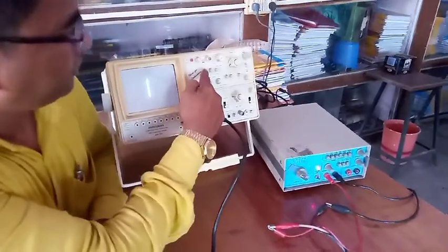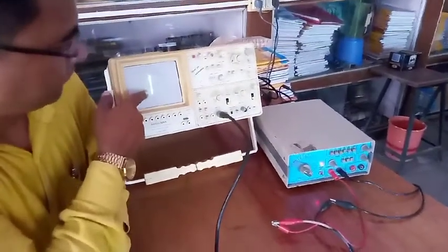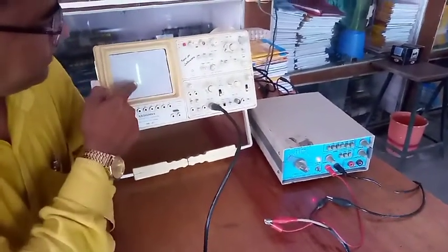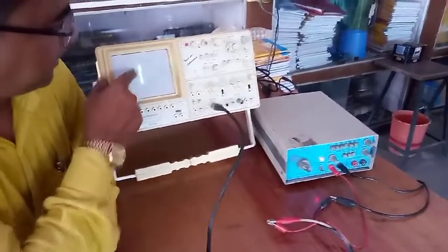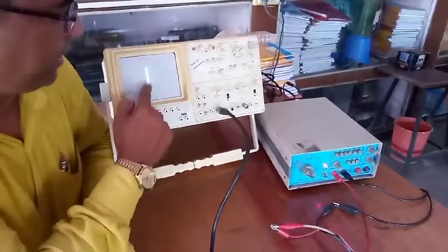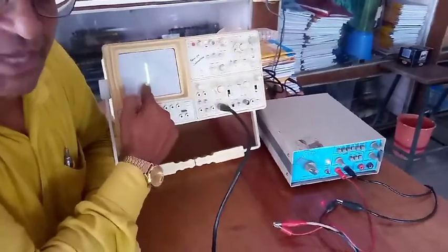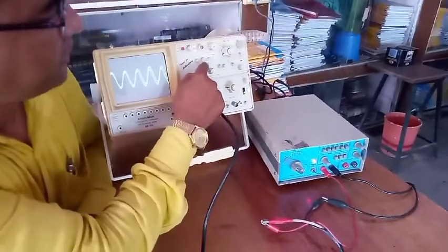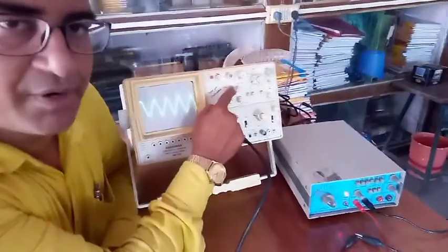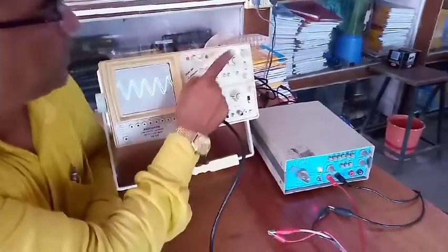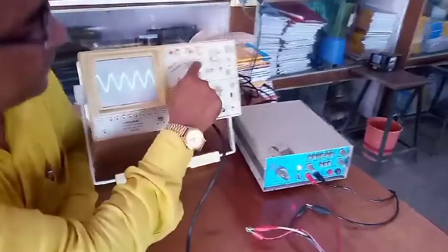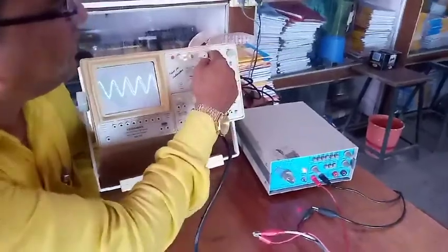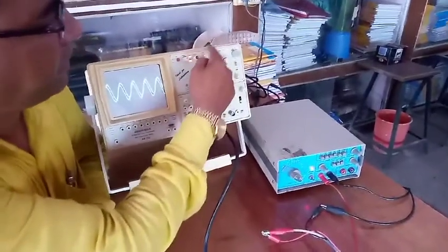Then the X1: if you want to measure only the y-axis, and you trace X and Y, ultimately one line is shown on the screen. You will be able to measure the peak-to-peak value, that is the VPP value, for the Y in a sine wave. Then coming back to this one, this is the vertical on and vertical off for the TV, that is the horizontal and vertical value for TV measurement. This is the frequency filter. Here you see AC, DC, HF, VHF, LF and sine. It is a frequency filter.